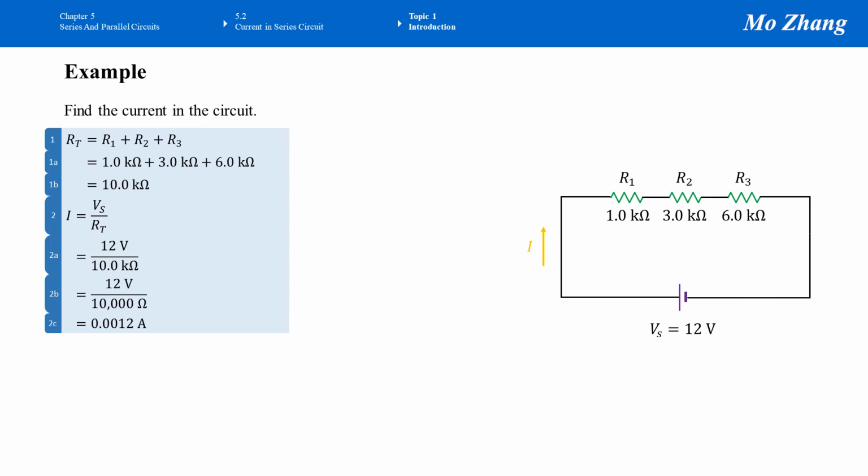We can even make the answer better using engineering notation. So move the decimal point to the right 3 times. That number portion is 1.2. Since we increase the number, we need to reduce the prefix by 1,000. So this is 1.2 milliamps. For our class, changing the number to engineering notation is optional. So either 0.0012 amps or 1.2 milliamp, either answer is right. Both answers are right.